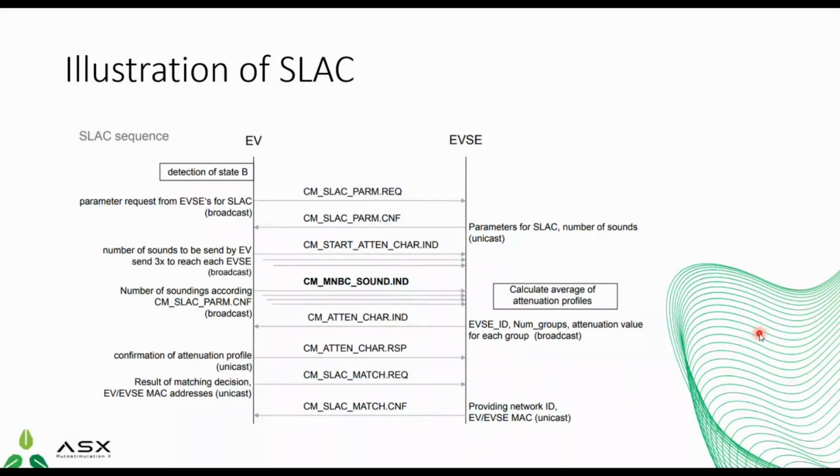Every time, the EV will send a SLAC request to the EVSE. The EVSE will wake up and send a response, and SLAC communication goes on. In our simulator, we have configuration parameters where you can change the different types of SLAC requests and their responses. You can simulate this. It is very helpful while developing the charger.